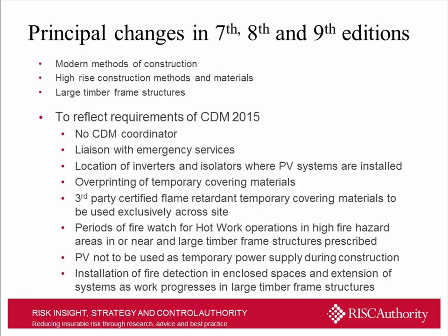We're finding instances where certified materials were subsequently being overprinted, which was ruining their resistance to ignition. A requirement for third-party certified temporary covering materials to be used exclusively across site rather than just in certain circumstances. Changing the periods of fire watch for hot work operations. Not allowing the use of PV as a temporary power supply during construction. And the installation of detection in enclosed spaces, and the extension of systems as work progresses in large timber frame structures to ensure that there's early warning of fire as soon as practicable.